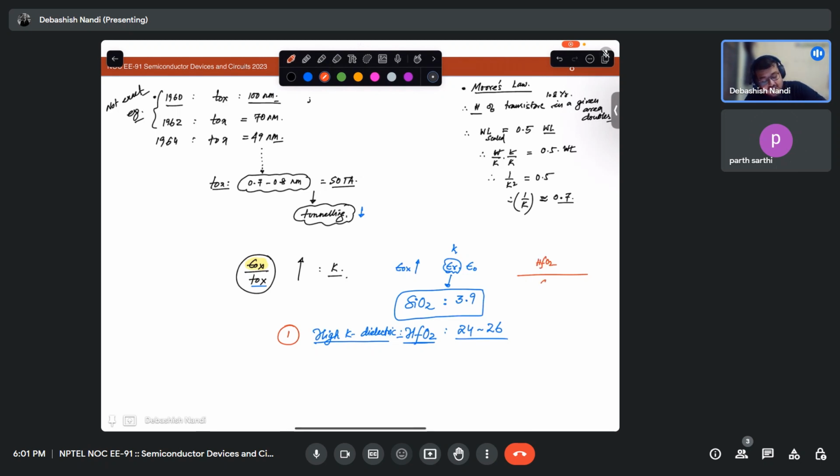It is hafnium dioxide and this is silicon. So this interface is very poor. So what people have come up with, they use this kind of structure. They use hafnium dioxide for the majority part of the oxide, because you see your tunneling does not depend upon your ER.